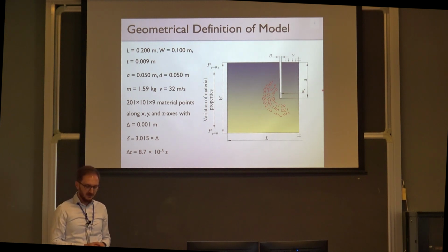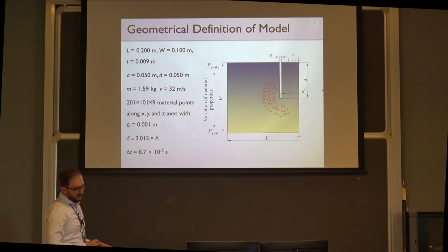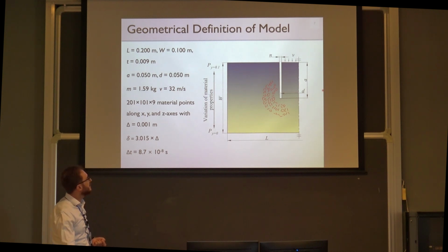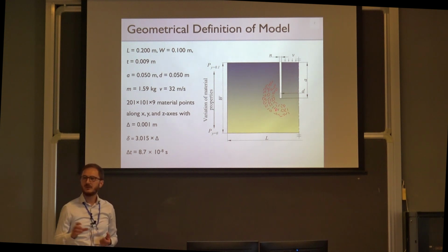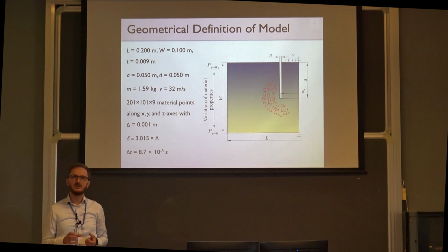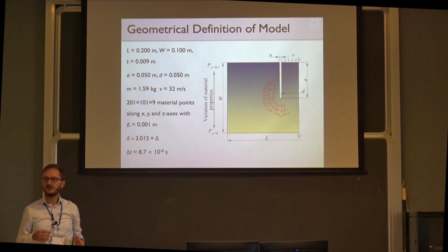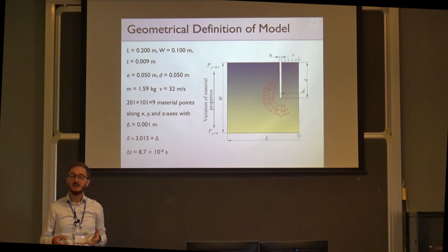In the figure, you can see the gradation effect on the material points through the vertical axis because we tried to model the functionally graded materials. These small red lines are the micro cracks located around the macro crack tip to get a toughening effect and accelerate the crack propagation.